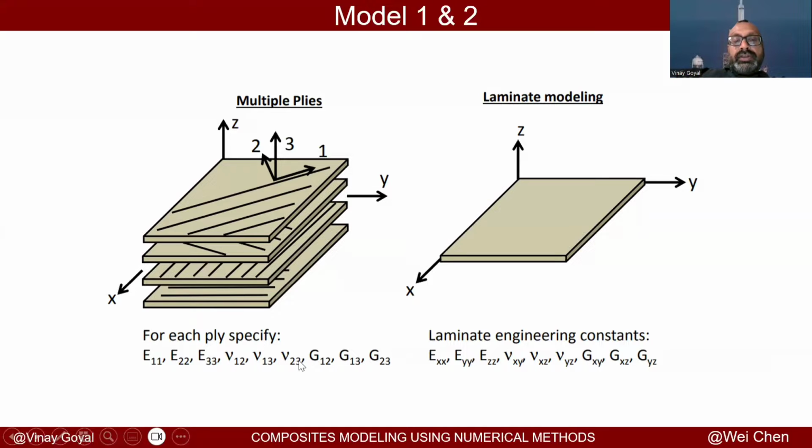You then have the three shear modulus. Shear is the resistance of angle change within the plane that you see here. G12, that's a shear modulus in the 1-2 plane. That's the in-plane direction. And that resists the angle change of, for example, two initially 90-degree oriented vectors like that. And this shear will try to prevent the angle change between those two vectors.